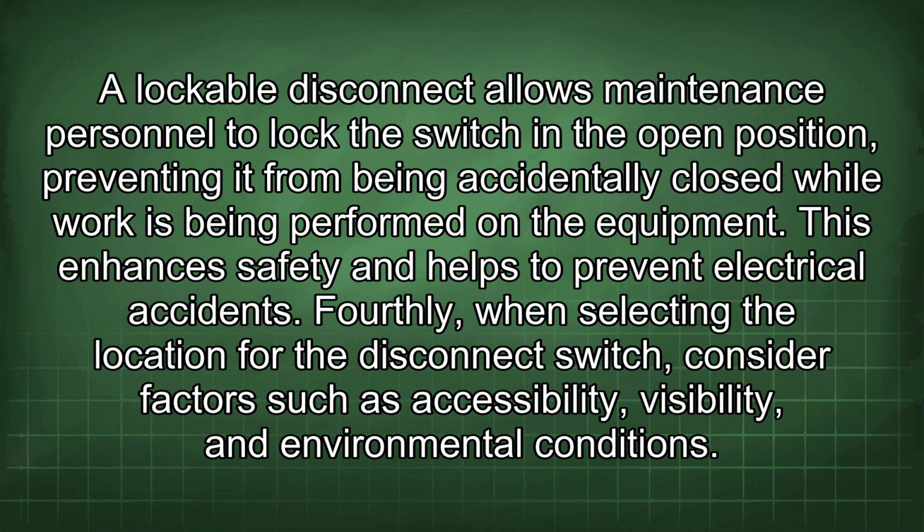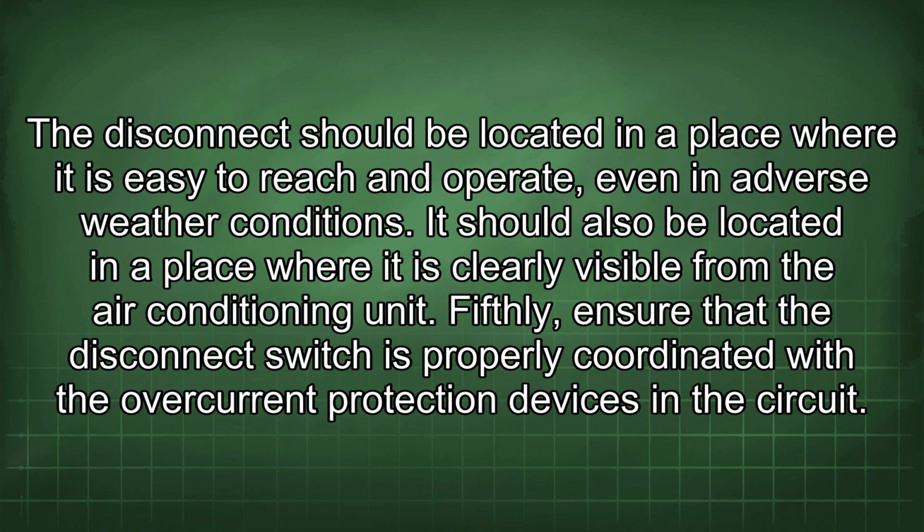Fourthly, when selecting the location for the disconnect switch, consider factors such as accessibility, visibility, and environmental conditions. The disconnect should be located in a place where it is easy to reach and operate, even in adverse weather conditions. It should also be located in a place where it is clearly visible from the air conditioning unit.